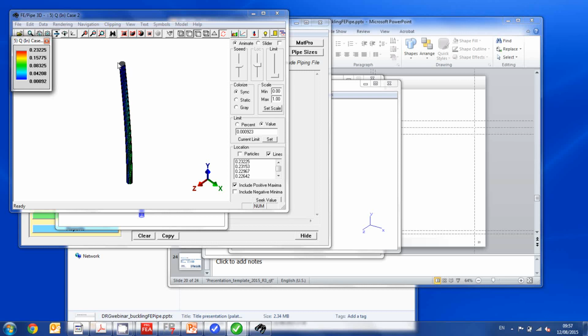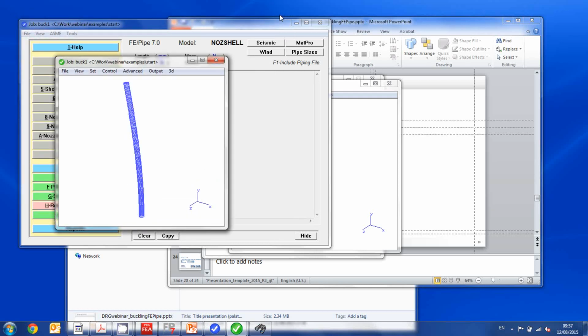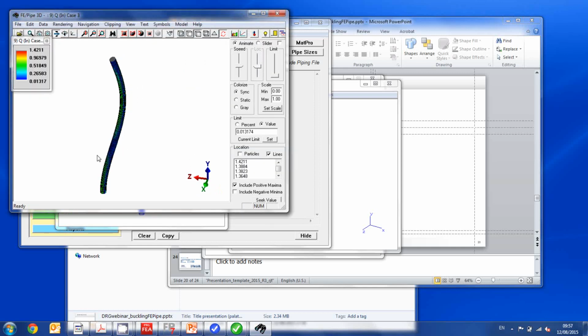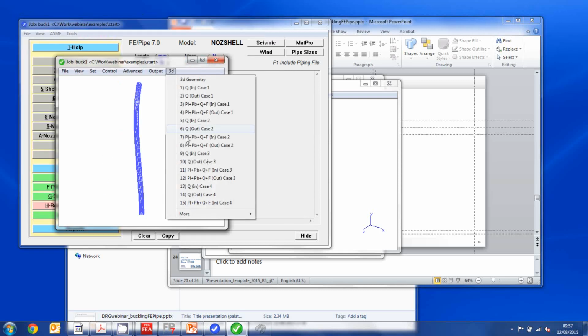As this is a cylinder, there are infinite buckling modes. You can buckle in every single direction. So therefore, 2 orthogonal buckling modes are solved. This is shown by load case 1 and load case 2. If we then go to load case 3, you'll see the more complicated second buckling mode, where you've got a free end here, but you see now you're getting 3/4 of a sine wave. And that will also have an orthogonal component in load case 4.